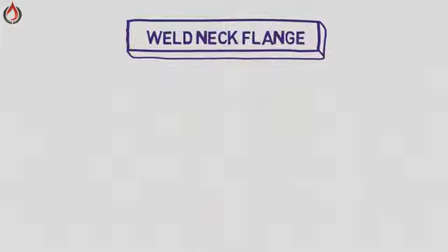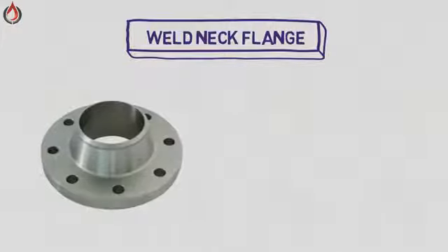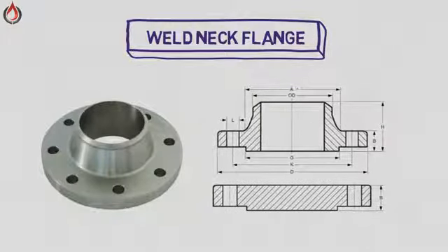Weld neck flange. A weld neck flange is the best designed butt weld flange available because of its inherent structural value and ease of assembly. It is designed to reduce high stress concentration at the base of the flange by transferring stress to the adjoining pipe.